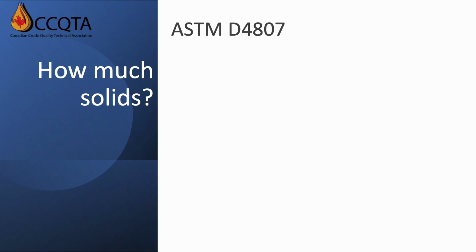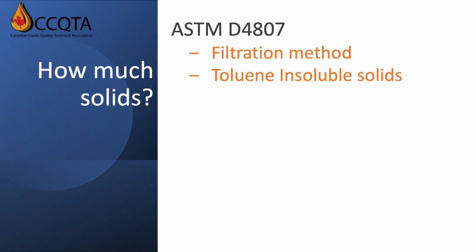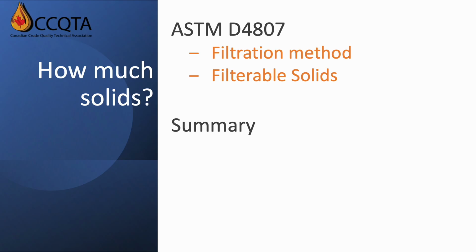ASTM D4807 is the most common method used for solids in crude and condensate. It's a relatively simple filtration method used to quantify toluene insoluble solids, otherwise referred to as filterable solids. Let me summarize the method quickly.